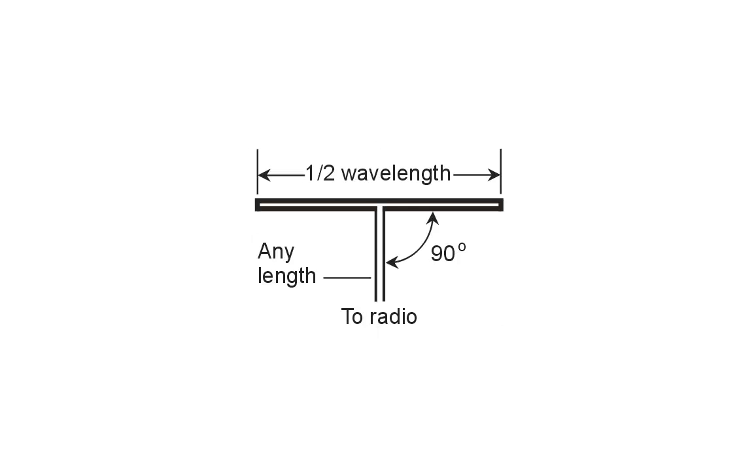And what does a folded dipole actually look like? This is pretty close to a literal diagram of a folded dipole, a half wavelength long, two parallel wires shorted out at the ends. The whole thing is a half of an electrical wavelength long. It's fed in the center, and then an open wire transmission line runs to the radio.